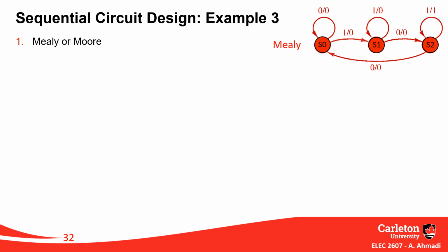Before doing that, I want to answer a claim which I made before. If I have a Mealy machine, can I make it a Moore machine? The answer was yes. The only thing you need to do is focus on your weakness, on the state which doesn't follow the rule, a state which might have two different outputs if you are in that state.